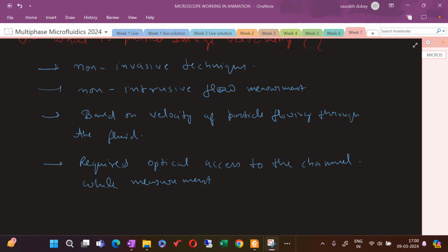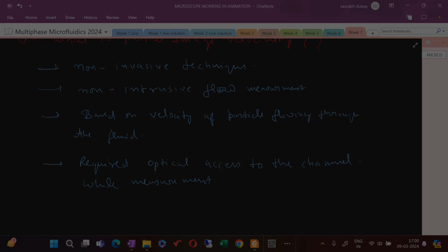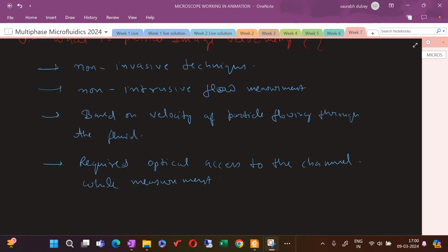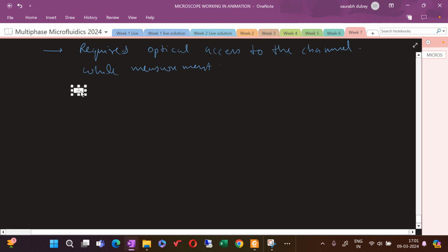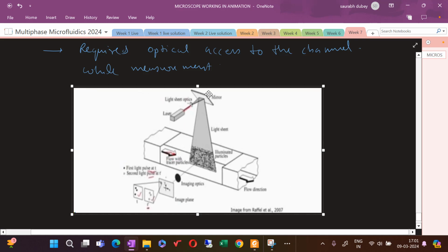We can have a pictorial representation of particle image velocimetry for your reference, so that you understand what we have discussed till now. These are the arrangements. The light source is the laser source, and this is illuminated in 2D. With 2D illumination, you have the particle-laden flow happening, and based on that you capture images through the image optics, compare the two images, and measure the velocity.